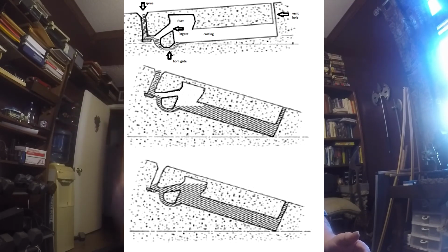You would have what we just looked at. But apparently this casting might have had some problems doing it that way. So they decided it would be better to force the issue to make absolutely certain that the very end of the casting solidified quickly, and directional solidification was established.